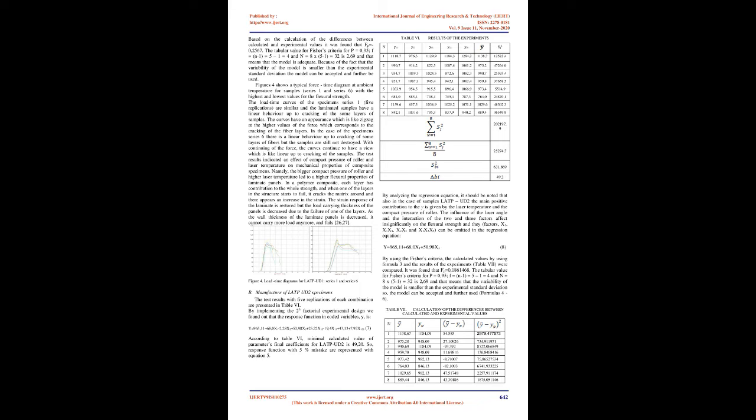By analyzing the regression equation, it should be noted that the main positive contribution to y is given by the compact pressure of the roller and the laser temperature. The influence of the laser angle affects the flexural strength insignificantly. The interaction of the two factors has a smaller effect on the flexural strength than the influence of the factors separately. The interaction of the 3 factors, with the coefficient of 0.57, also has a negligible negative effect on the flexural strength. So, they can be omitted in the regression equation.